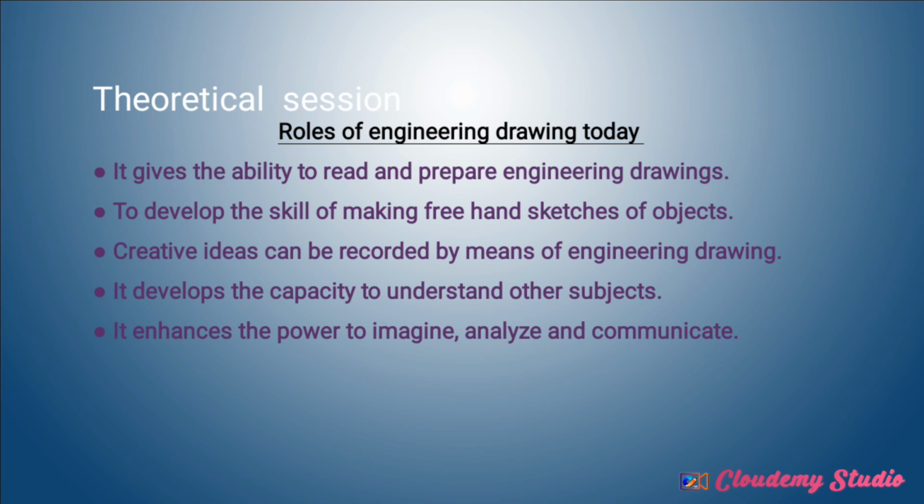If you are looking at the aspect of imagining something, we apply that mostly when we are dealing with orthographic projections, drawing diagrams in first angle and third angle. So if you are given the views, you have to imagine those views in 3 dimensions, because most of those views, as we discussed in class, we said an orthographic projection is a type of projection that has only 2 dimensions, that is the length and the width.